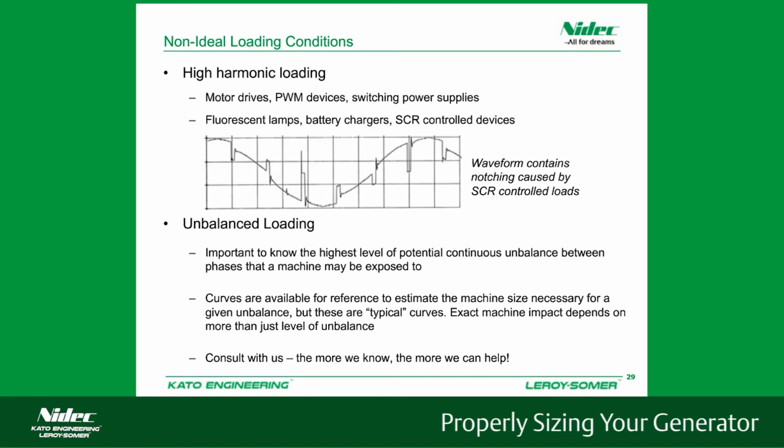It's important to know the highest level of unbalanced loading so we can size the machine accordingly. We have curves available for reference to estimate the machine size necessary for a given unbalance, and the exact machine impact will vary unit to unit. So the more we know ahead of time, the more we can help with that.